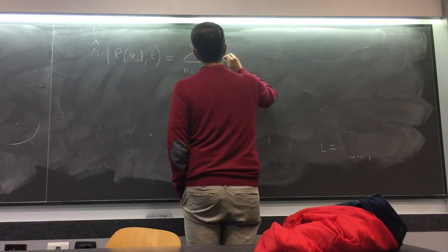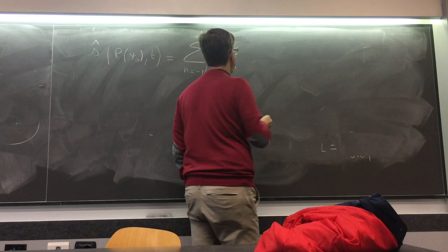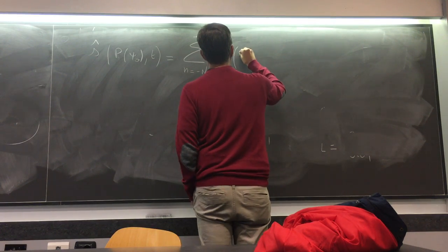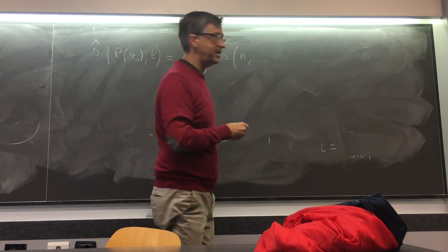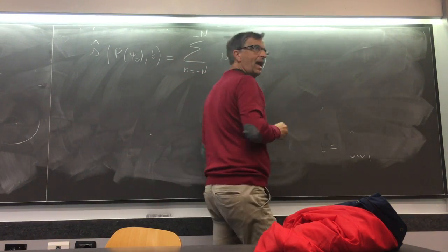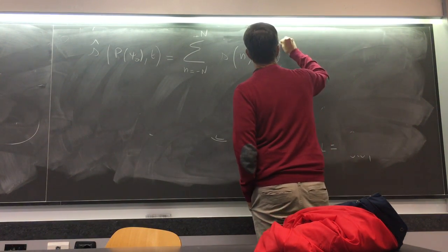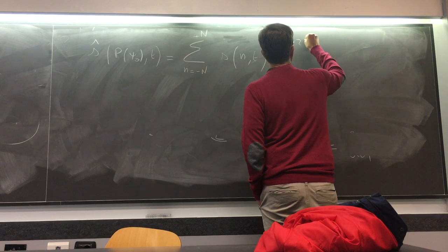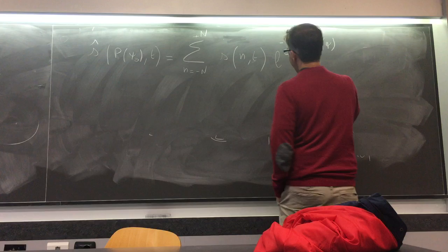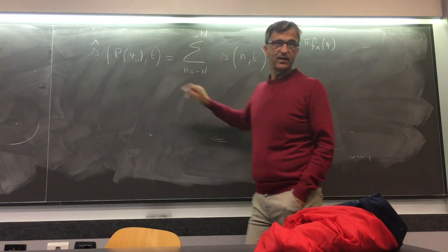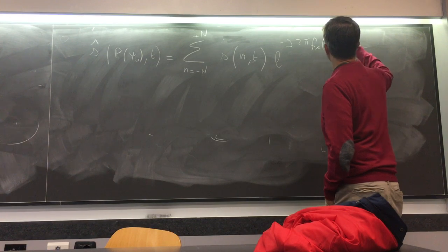Then you point here the signal received from all the antennas. So the signal depends on n, the position of the antenna, and on time. And I have to put here some coefficient. The coefficient is exponential of minus j 2 pi fx, which depends on the angle in which I want to point the antenna, multiplied by x. Okay?